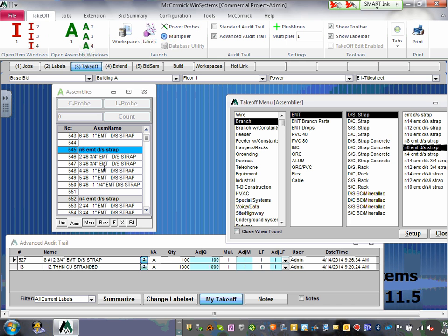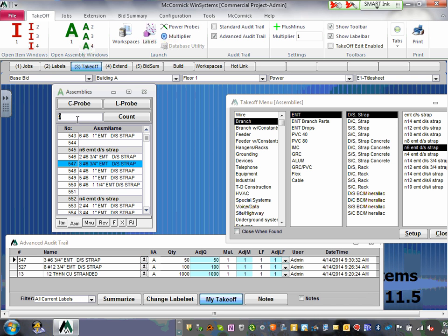In order to drop, so if I want to drop 3 conductors, let's take this like an air handling unit. Say I have 3 conductors, number 6 in 3/4 of an inch. I have 50 feet of these. Type 50, hit enter. Gentlemen, you have just entered 50 feet of a number 6 conductor, 3 conductor in 3/4 of an inch. That will go to a rooftop unit, right? Or a chiller or whatever, a smaller one. So that's your conductors.